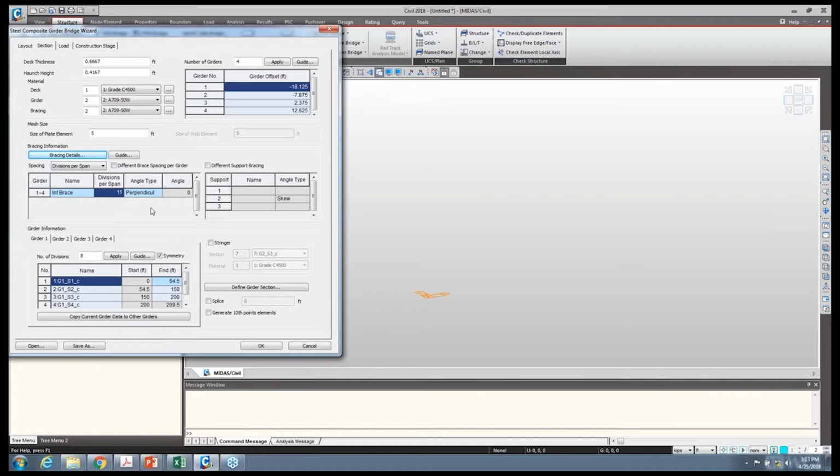So now as we do this, you'll see that the angle sections appear under the bracing. I'm going to use a typical bracing system, not a single beam or a diaphragm brace. The section I took is a V brace, or I like to refer to it as an inverted K, but it's the same methodology. As we go ahead here, we're going to change our angle sections. We have our interior brace, and then we are good to go.